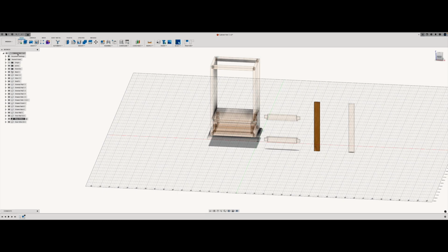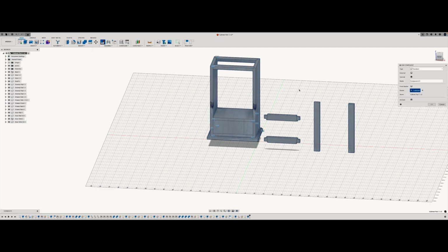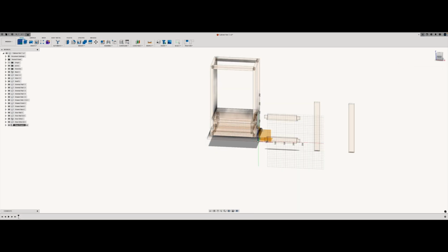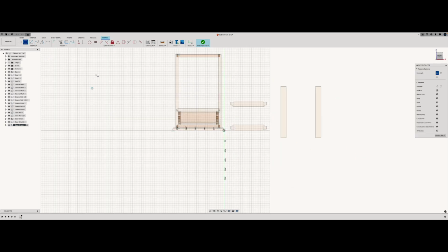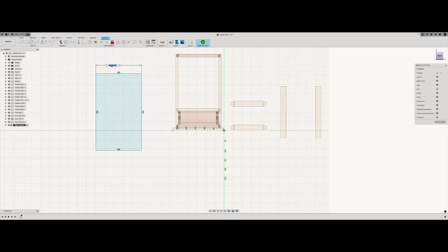So let's go and make this guy active. Add a component. Draw, not draw, sorry. Door front. Sketch that guy off here. Capture the position. And we said 160 plus 6 plus 6. And then this way we said it was going to be 280 minus 30 plus 6 plus 6.